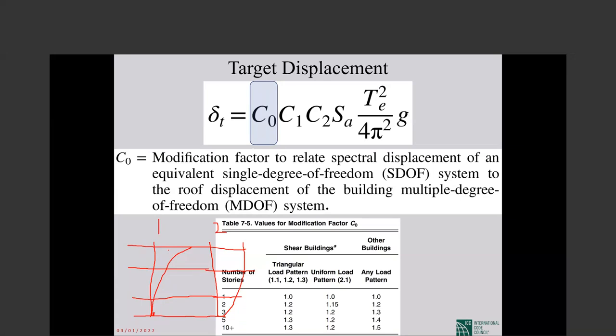A frame, you can neglect the shear deformation in beams and columns of that, but the general form of the frame behavior for a multi-bay, multi-story frame is like type 2. So it's shear type deformation, but you neglect the shear deformation in elements.